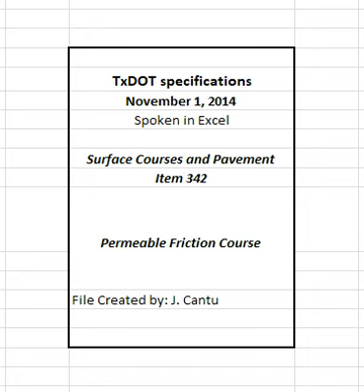4.7.3.4 Screed heaters. Turn off screed heaters to prevent overheating of the mat if the paver stops for more than 5 minutes. The engineer may evaluate the suspect area in accordance with Section 342.4.9.5, Recovered Asphalt Dynamic Shear Rheometer, DSR, if the screed heater remains on for more than 5 minutes while the paver is stopped. 4.8 Compaction.